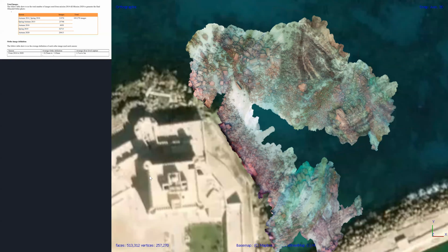As you can see, here is the fort of Qaitbey. And this is the whole area we covered till now by taking 103,000 images. The ground sampling distance, which means the pixel size for the whole site, is between 0.5 centimeter and 1 centimeter per pixel. That means I can zoom in until I see the grains of sand for the whole site, which is something very special for all of us. We still will cover this mid area. We didn't cover it yet because it is the most challenging part, covered with a lot of sand and not too many features. So I think in the future, we're going to start to focus on covering this area.